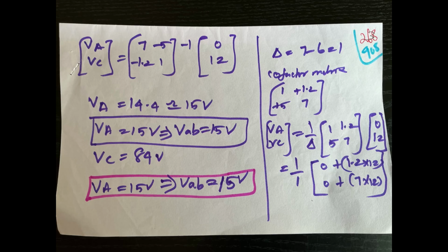Mark the terminals AB of the remaining two terminals. That is, VAB is the terminal V Thevenin voltage, that is the open circuit voltage, 15 volt. We find it by the mesh method, that is, V is IR, applied in this method.